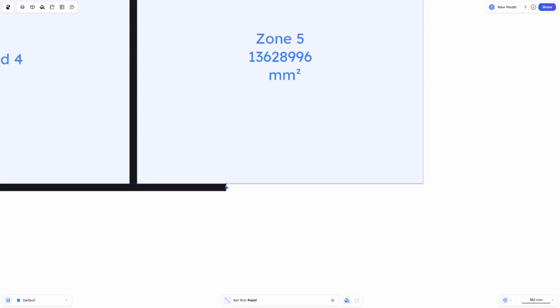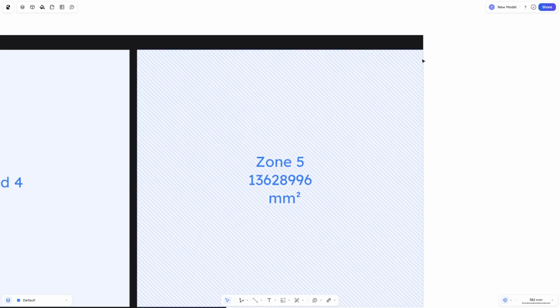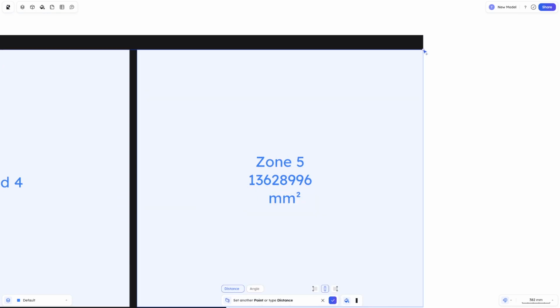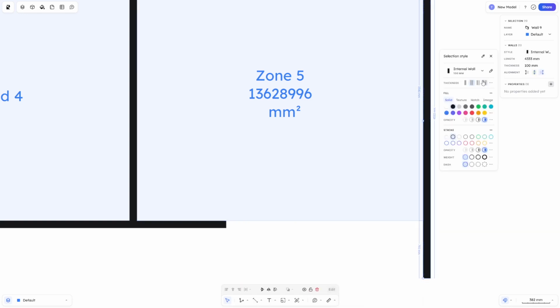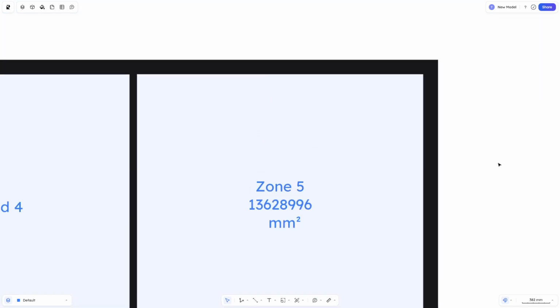What I wanted to do is draw a floor plan zone, and now that sits a divider. So basically that's the dotted line to say, I think that's worked. What that does is, if I draw this wall down here now, and go a bit further down, let's say, pop it to the outside, make it an external wall because it is, and that's snapped there.